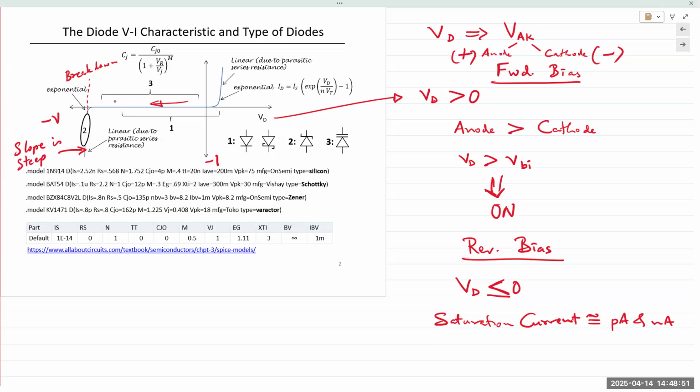So it's one of the properties of a semiconductor diode that once the junction breaks down, there's a flood of charge carriers, and the level saturates. Current can keep on increasing while the voltage across the diode is held nearly constant. And this property is actually used and implemented in something known as a Zener diode.